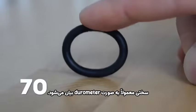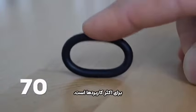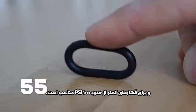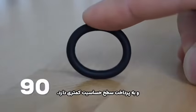The same material is often available in a range of different hardnesses. The hardness is typically expressed as the durometer hardness. 70 is a fairly typical hardness and is good for most uses. 55 durometer is much softer and is a good choice for pressures below maybe 1,000 psi because it is easier to install and less sensitive to surface finish.